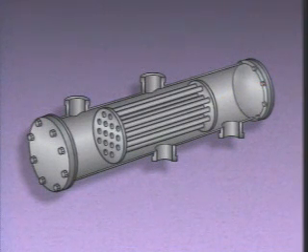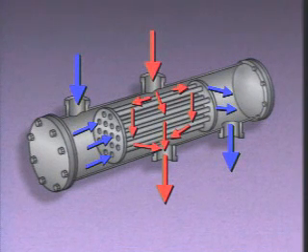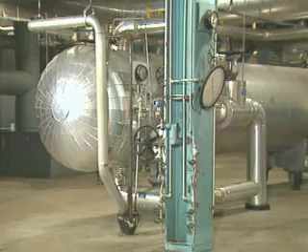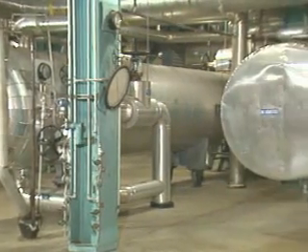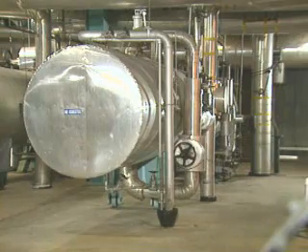The heat exchangers that are used as condensers in the condensate and feedwater system have condensate in the tube side and steam from the gland steam system or the air removal system in the shell side. During the heat exchange process, the steam is cooled and the condensate in the condensers is heated. U-tube shell and tube heat exchangers are used as heaters to heat the condensate and feedwater that moves through the system.